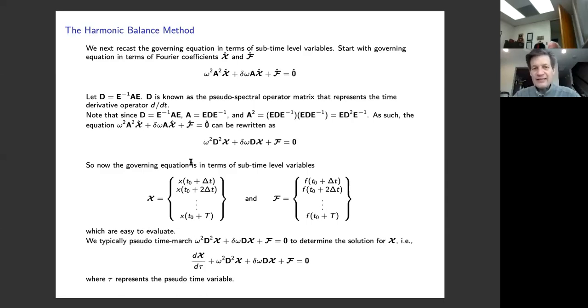And then we can inverse Fourier transform to compute back to the frequency domain results, which we might want to deal with. So that just gives you the gist, hopefully, of how we apply the harmonic balance method for cases where we're dealing with non-analytic functions where we can't use the classical harmonic balance approach.